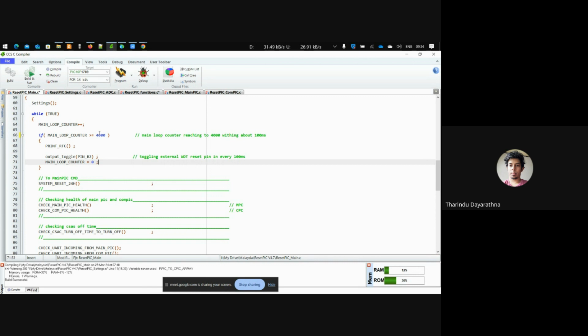If I don't need exact timing, I create timing using this other function. You see, I did not use any other timers, so the code is very simple. This will definitely run this function. If the timer gets a problem, this will stop running, which means I am not resetting the external watchdog timer. That external watchdog timer will then reset the reset pin. I wrote a very simple line.